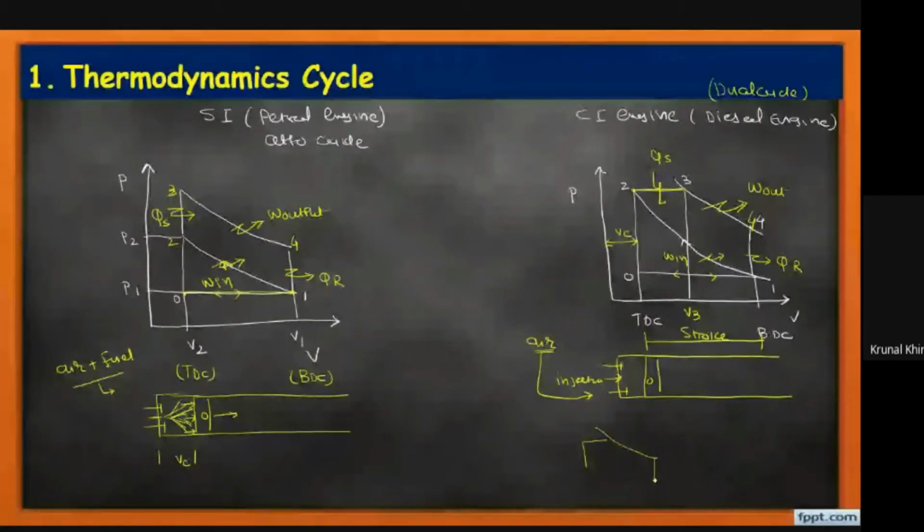So this kind of cycle diagram is that. It is a combination of the Otto as well as the diesel cycle, and this kind of cycle is known as a dual cycle. The dual cycle is used for high speed diesel engines. So this is the operating cycle, or thermodynamic cycle difference, between the petrol and diesel engine, or SI and CI engines.